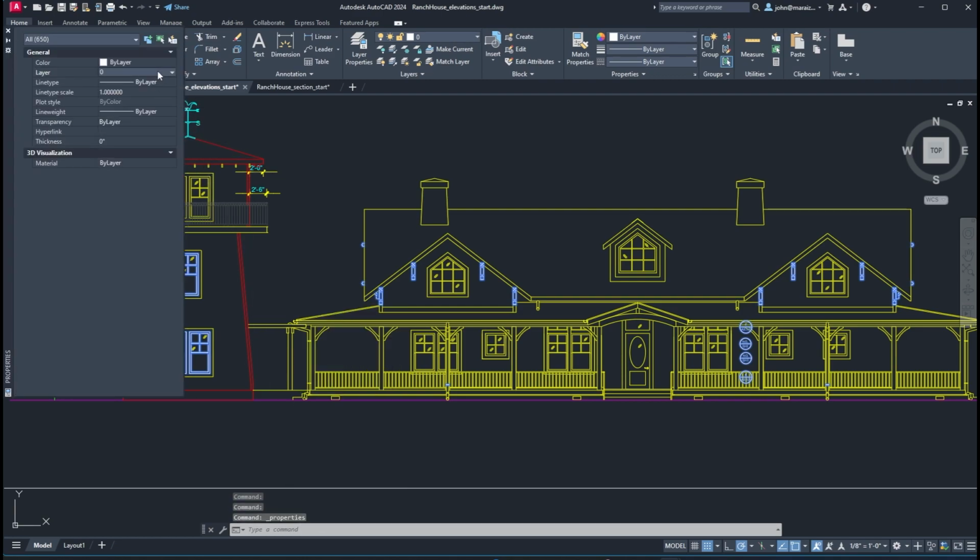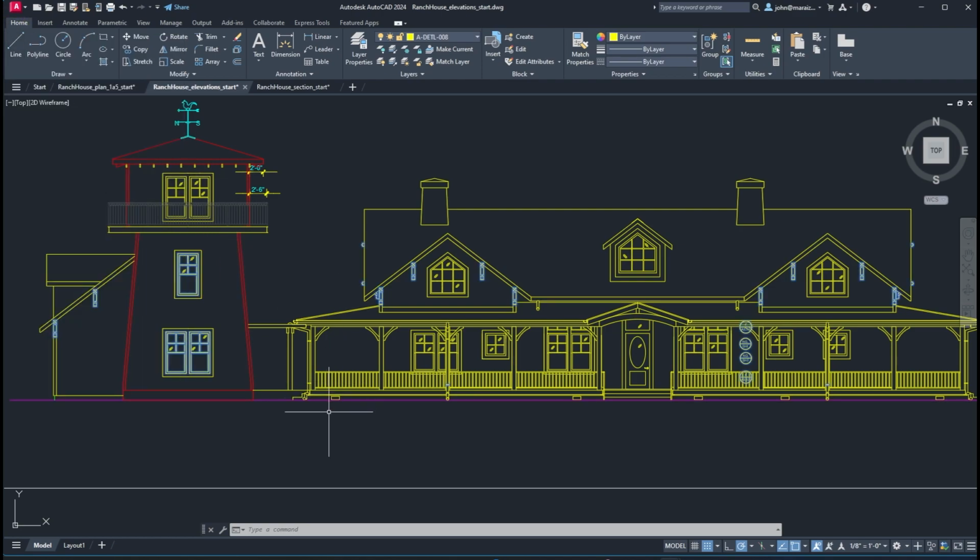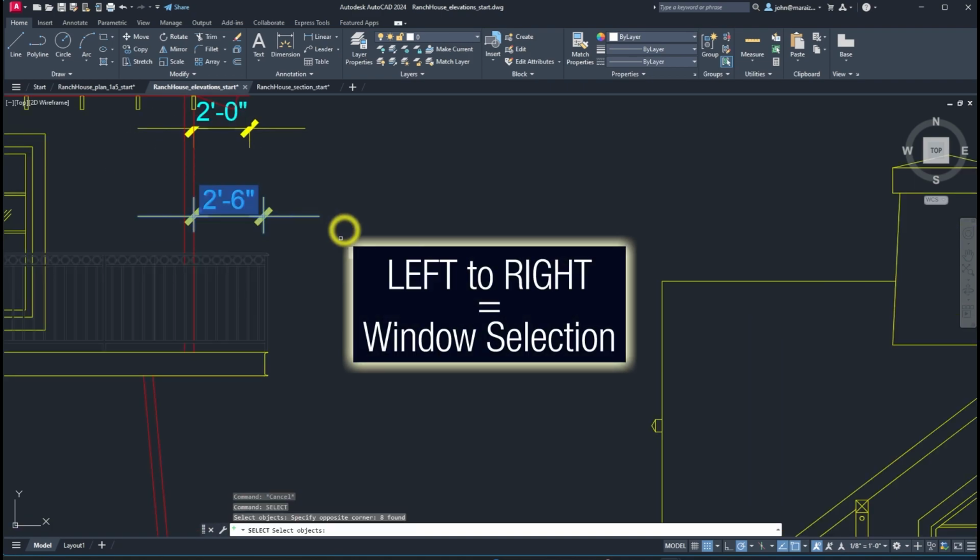Assign an appropriate layer for most of the selected items. In this example, some annotations and dimensions should be hidden, and not on the detail layer that I chose. Select them individually and assign them to a frozen layer.